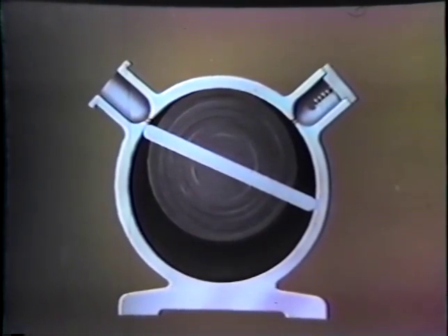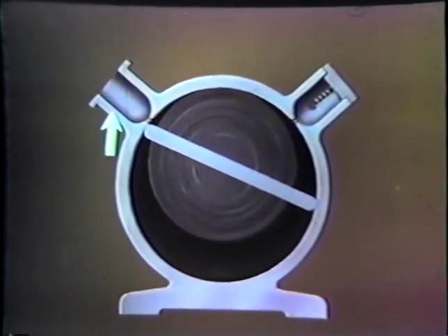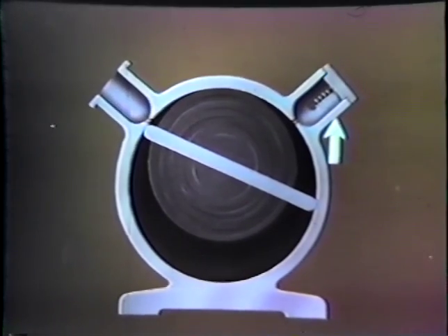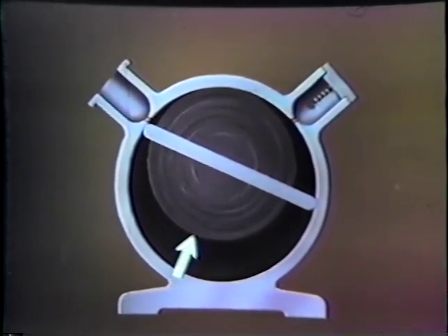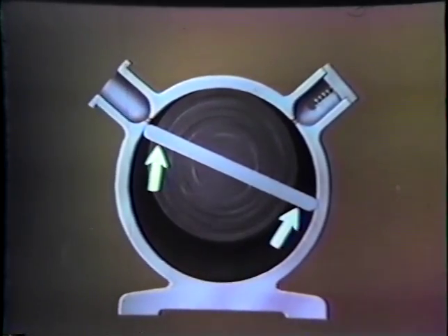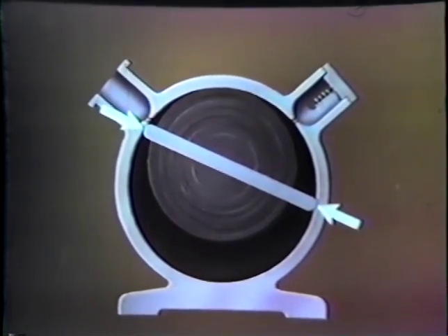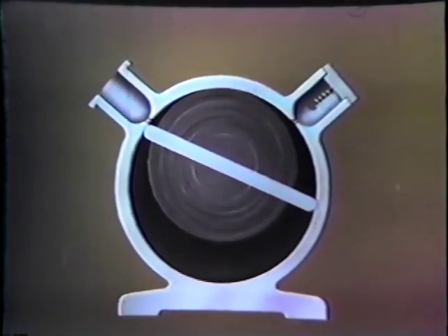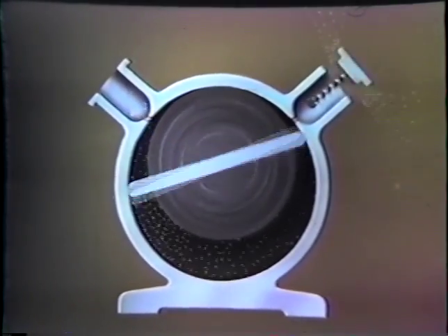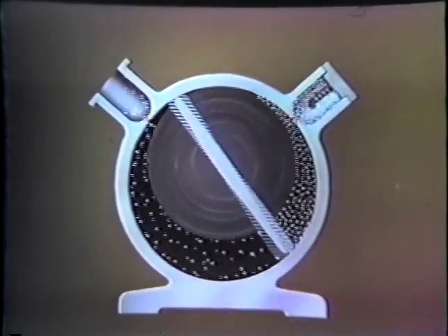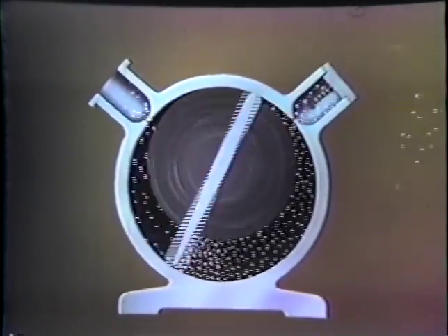The rotary-type pump consists of a stator case with an intake port, an outlet port and valve, and a cylinder mounted eccentrically within the stator. It is equipped with spring-loaded vanes that make a seal with the stator, aided by an oil film. Air is swept around the chamber and is compressed as it reaches the outlet port.